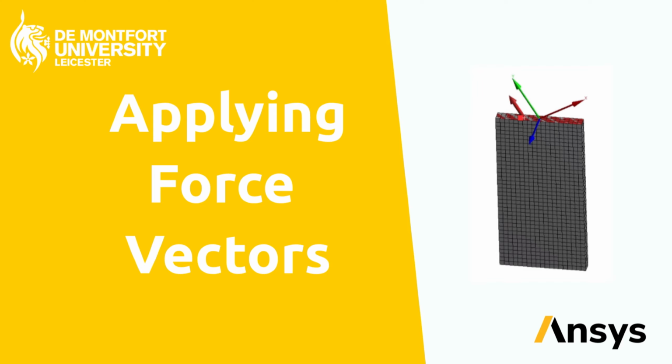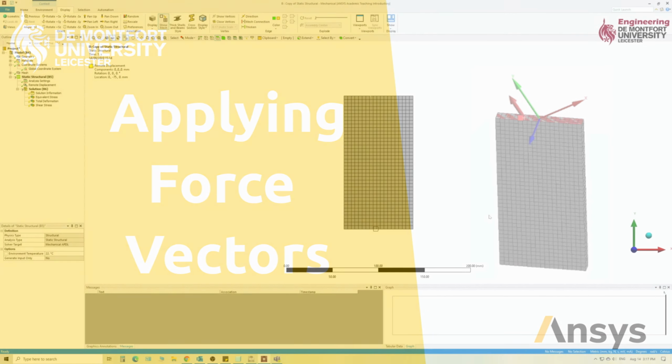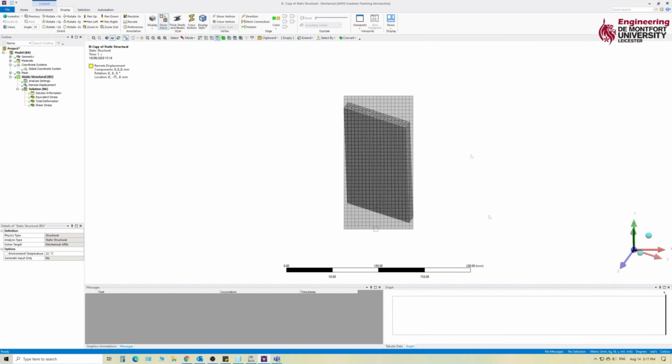In this video, I'm going to be having a look at how we can deal with force vectors and how we can apply them to our components. Here we have a simple plate of steel, and what I would like to do is apply a force that is clocked at 30 degrees from the vertical, so pointing up from the surface this way.